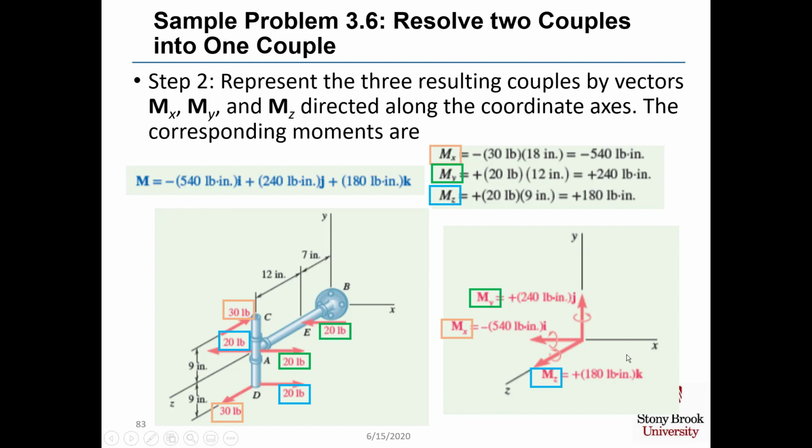The picture on the lower right shows that we can move the moments from their original position along this assembly and move them to act along the coordinate axes. Because, unlike forces, moments can be moved in space as long as where you move them is a parallel axis.